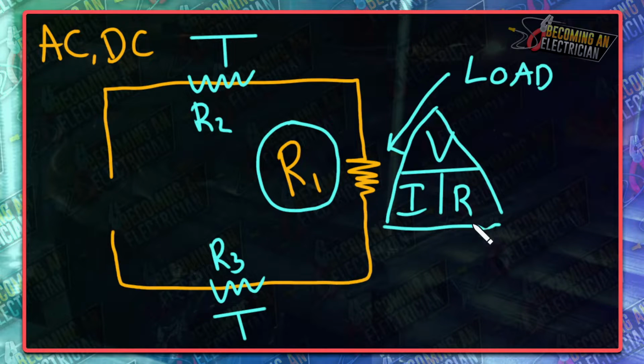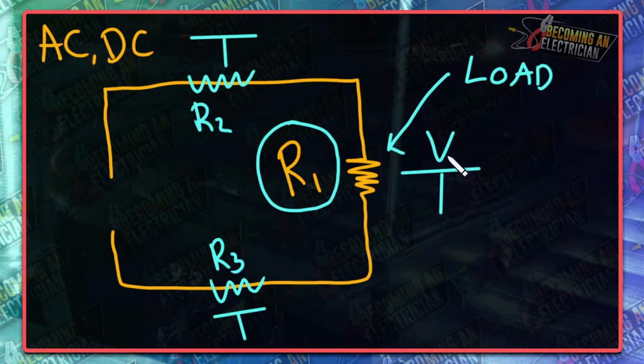Before we go further, when it comes to a resistive load, a purely resistive load is something like a baseboard heater. You're going to see it called a BBH out there. Baseboard heaters are still very, very common when it comes to condos and apartment buildings. If you notice, they always put baseboard heaters underneath windows. It's to create kind of like a shield, so that when the cold comes through the window, the baseboard heater is blocking that cold from coming in.